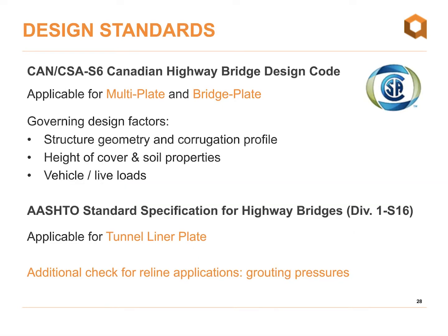In terms of design standards, we actually did a presentation at the end of last year on design procedures for these buried steel structures. So you can always go back and reference that. We won't talk about that too much in this presentation. But suffice it to say, we design multi-plate and bridge plate according to the CHBDC design code. So typical governing design factors are, of course, structure geometry, corrugation profile, and the loading conditions, so height of cover and vehicle live loads.